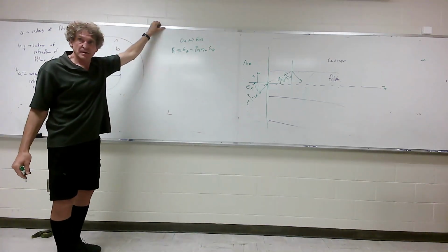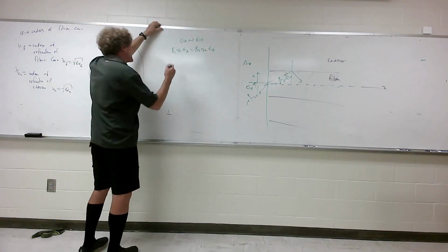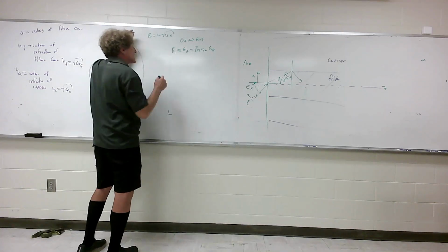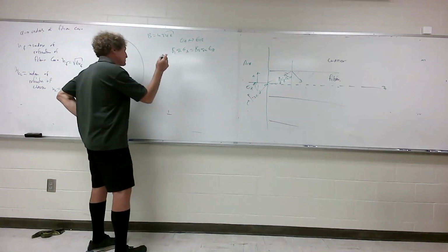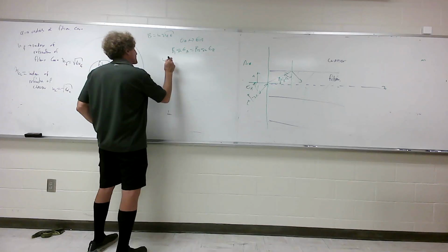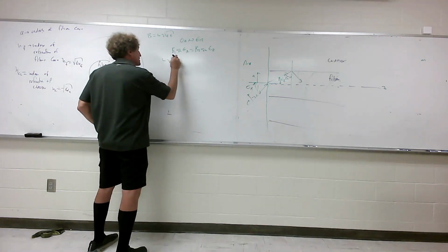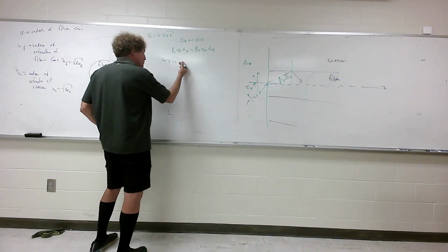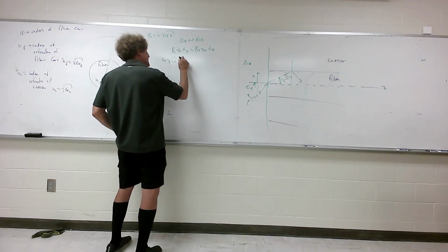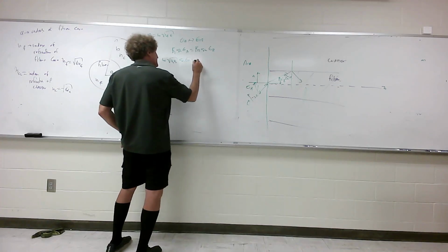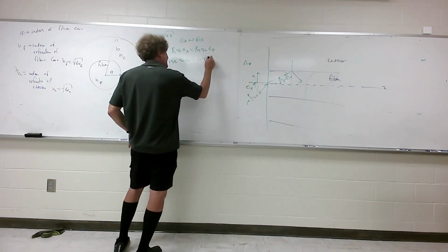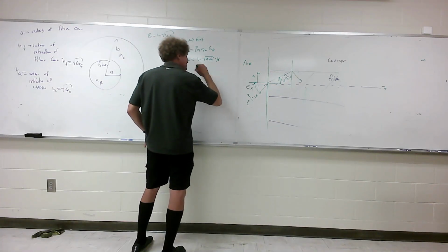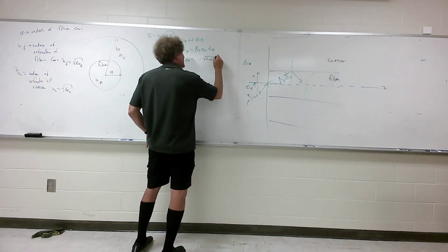Can y'all follow me on this one? Now, because beta in general is omega times the square root of mu epsilon, that appears on both sides. I'm putting this down only one time, I won't afterwards. Omega times square root of mu naught epsilon naught, times square root of mu relative, which is 1, times the sine of theta A equals beta 2, which is omega square root of mu naught epsilon naught, times the square root of epsilon, and this is the epsilon of the fiber right here.